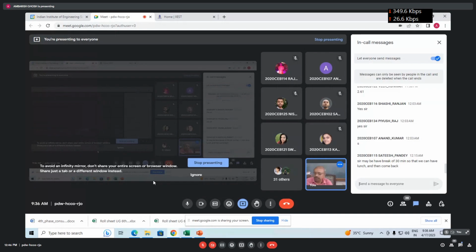Sir, what if the diameters of the piles are different? The different pile diameter will be decided earlier already. That has been decided already from capacity point of view. First you get the soil report, then the loading from the column, then you decide what will be the diameter. After that you go for the spacing. This is the step. Diameter you have decided already.